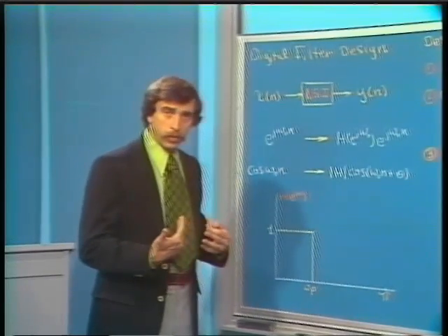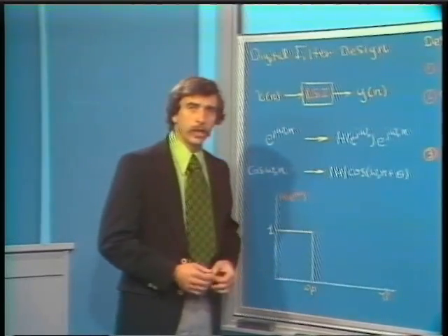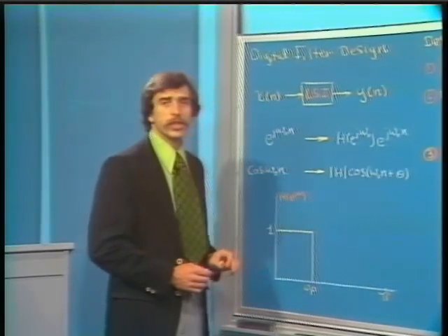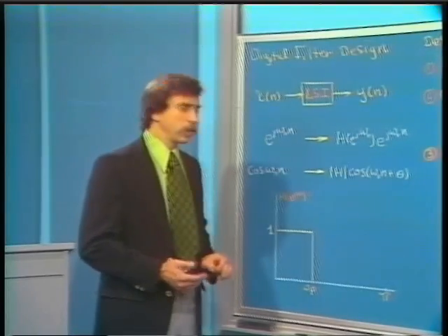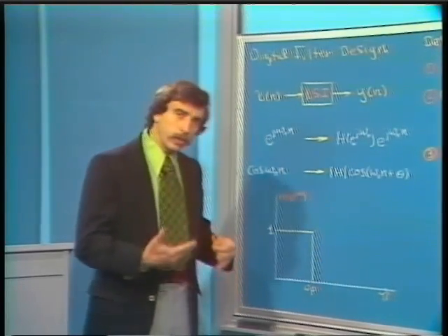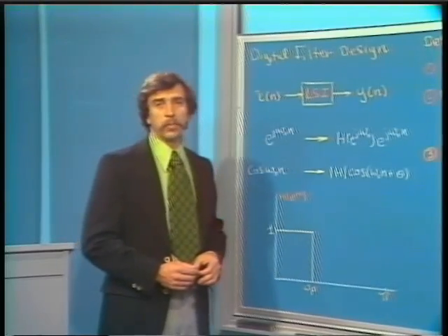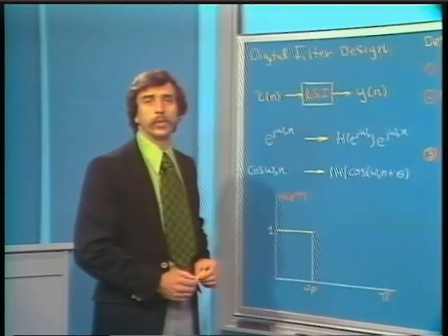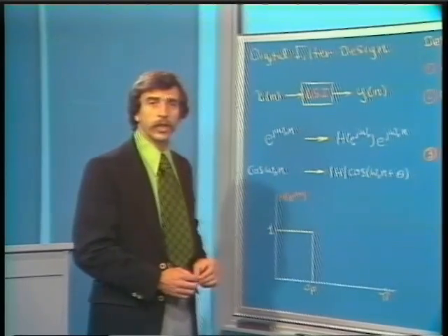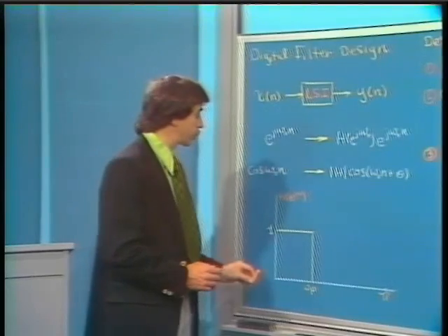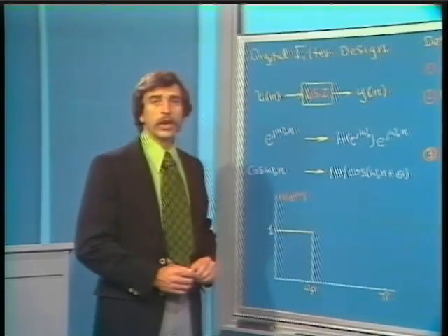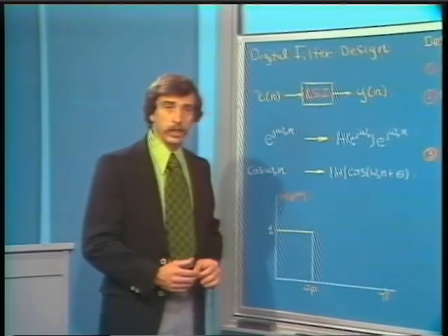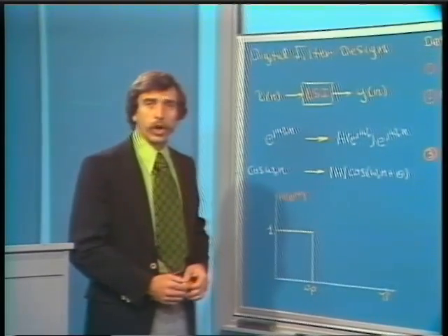We can talk about a wide variety of problems, in fact, where the desired frequency characteristics are not piecewise constant as they are in the frequency selective filter case, such as, for example, the case of a differentiator, in which case the desired frequency characteristic is in fact linear with frequency, or the inverse filtering problem where the desired frequency characteristic is in general of a somewhat arbitrary shape.